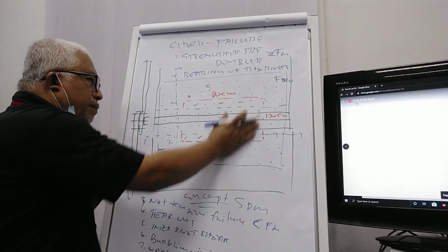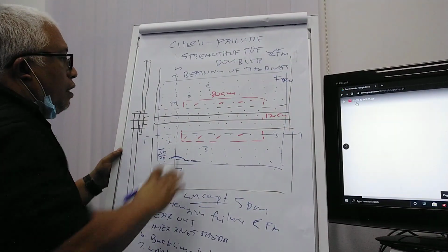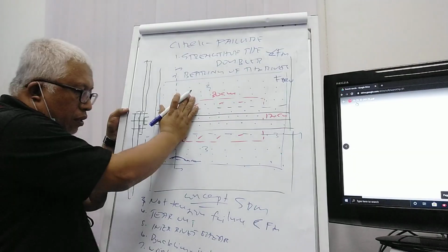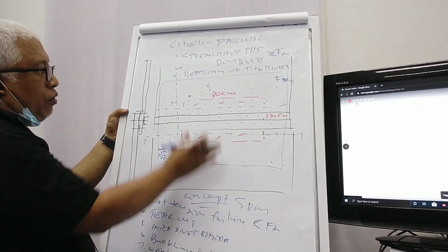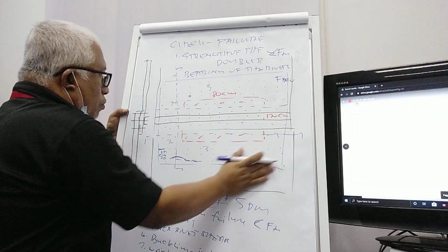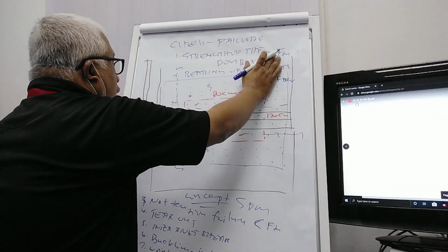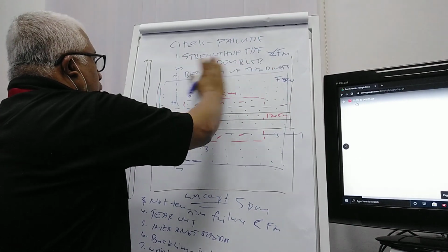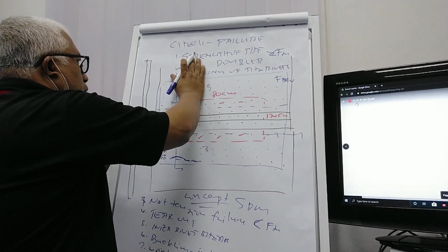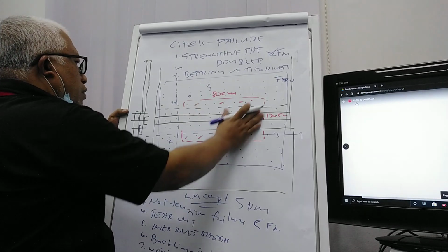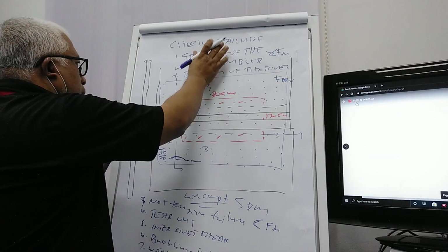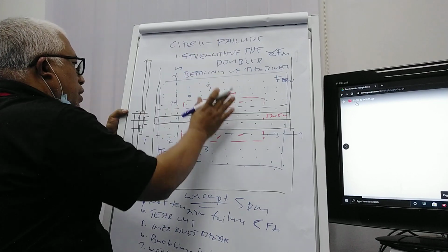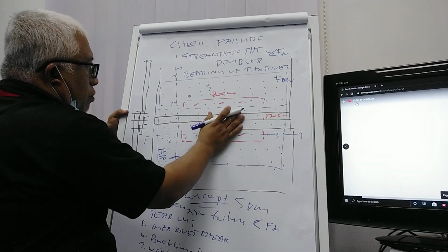So this concept repair, which is from SRM, and then after you draw the concept repair, the next step is to check the failure modes of this repair. So which is the doubler strength, whether the doubler will be able to carry the load, which is the load lost after you lost the area. The doubler load capability should be higher than what you have lost after you cut this one off.